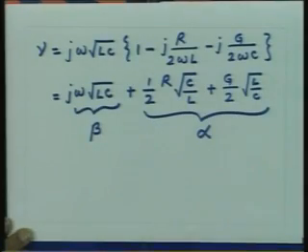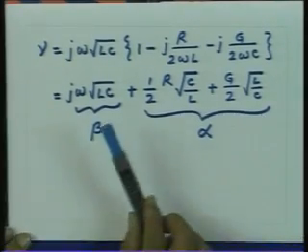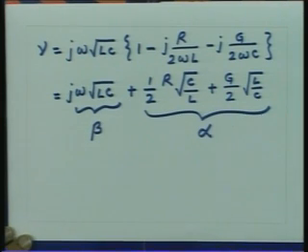However, in case of a real line, even with a small loss, you have this value alpha, which is related to R and G. So, as the wave travels, the amplitude reduces slowly as it travels on this transmission line, but the amplitude does not vary rapidly. There is a small decrease in the amplitude. So, over a short distance, if I do the calculations, the line can still be treated like a lossless line with the phase constant, which is equal to omega square root L C.